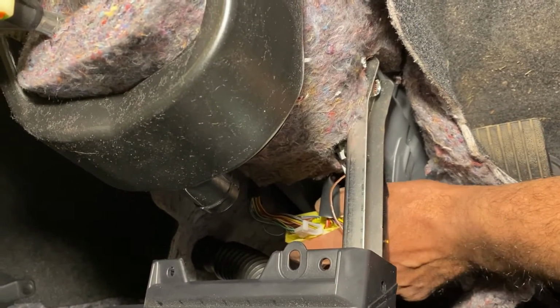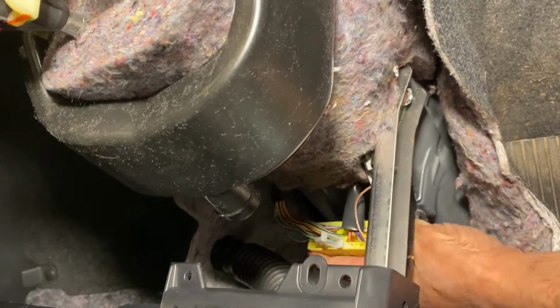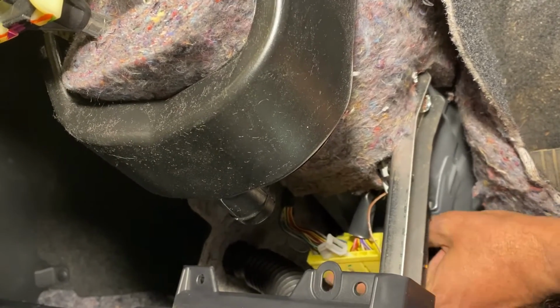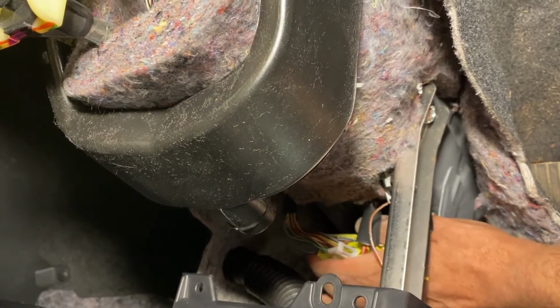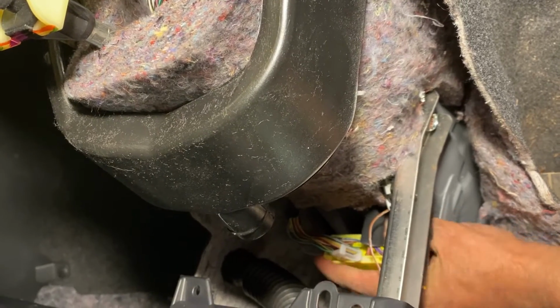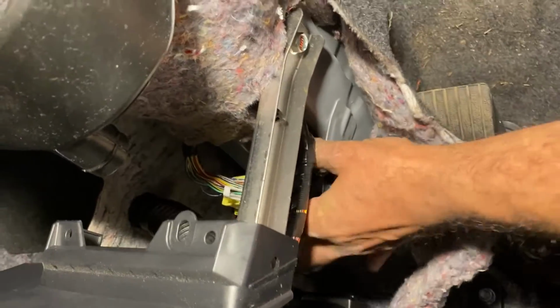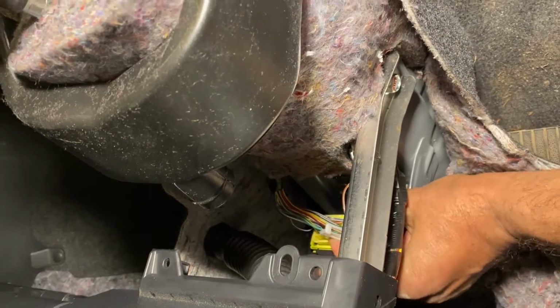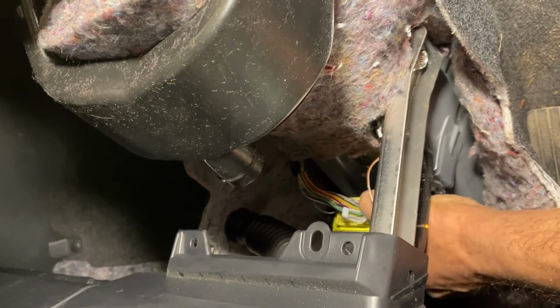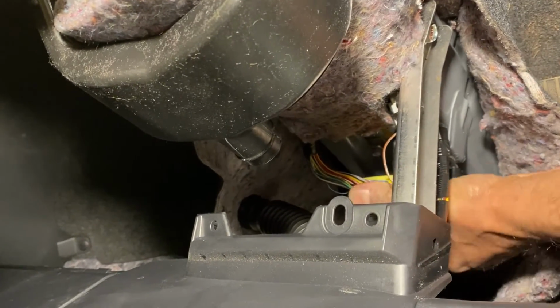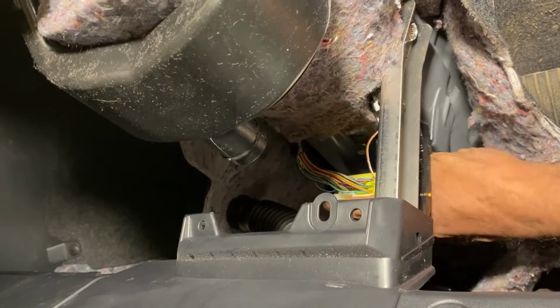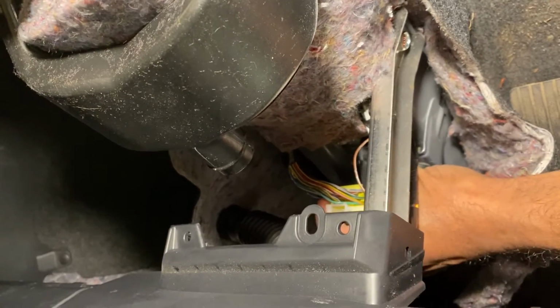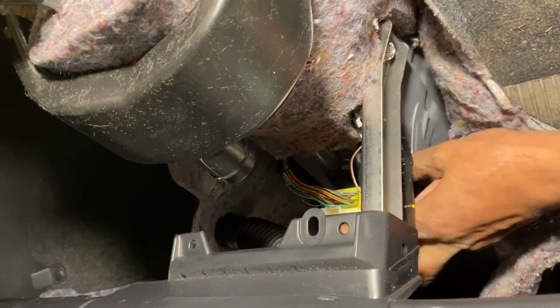So I removed the EEPROM, and I let the processor cool down, which I left for like 5-10 minutes, because even before I removed the EEPROM, the processor was really hot, not even 2 minutes plugged into the external power supply. So let's see if this is going to change. Hopefully it's not, since we already have the 60 ohms, so I don't think anything is going to change, but let's try. Make sure it's connected, and I have the battery disconnected. All right, and I still have like 56